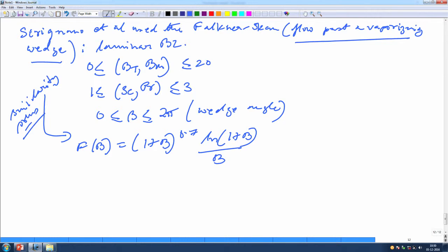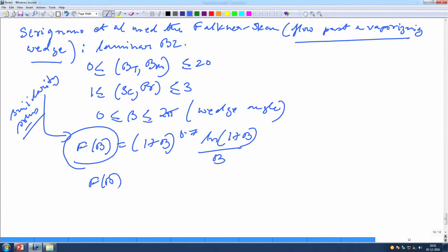There are some interesting exercises that people did. People studied the variation of this F(B) in the current context. They found that F(B) varies from basically 1 to 1.285 as B, which is the Spalding heat or mass transfer number, varies from 0 to 8.